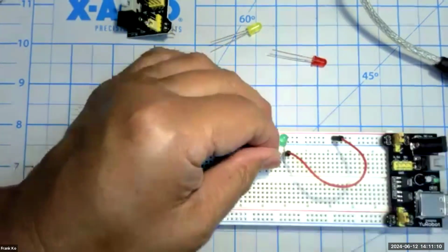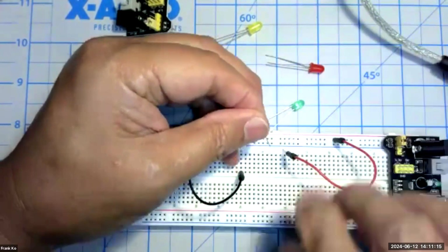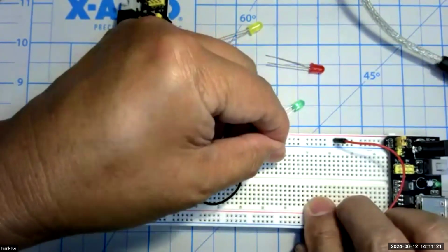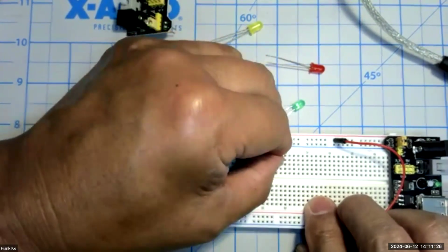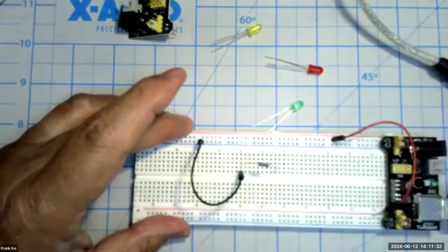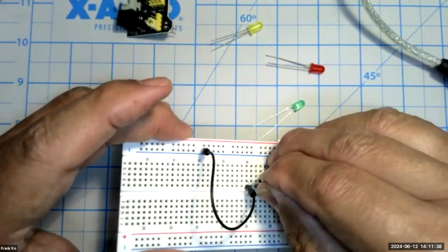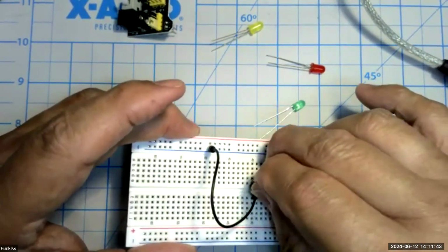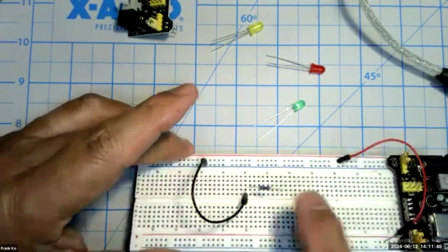Very carefully position this into the hole that you want. Perhaps the LED's in the way; this may give you a better view. So we're going to position this into 32D. Right there is 32D. Once I have it aligned to the hole, I will very carefully push straight down, just a minor amount of force. I'm going to take the other end and align it to 40E, and very carefully, again, grabbing the wire near the end, push it down firmly, and that's it. You don't have to crush the resistor onto the board in order to make contact.